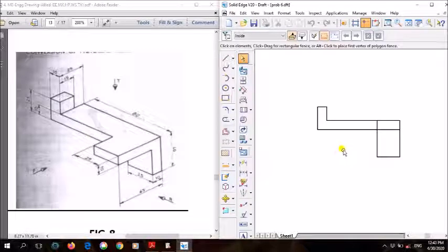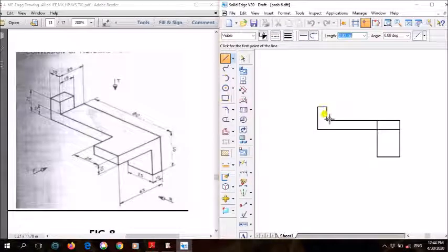There is another section that is not visible that we need to draw. You can see here, this is the solid whole part, right? Whatever this projection is, only up to here it is 15 mm. Whatever this 10 mm is, there is no projection, it is blank. So whatever this leftover part is, that is solid. When you see from the front view, there is an edge on that side also, and that edge is not visible. So we need to draw that edge here using a dotted line. Clear? So here, using a thick dotted line, start from here and end it here. Like this, you need to show a dotted line. Clear? So this is the front view.